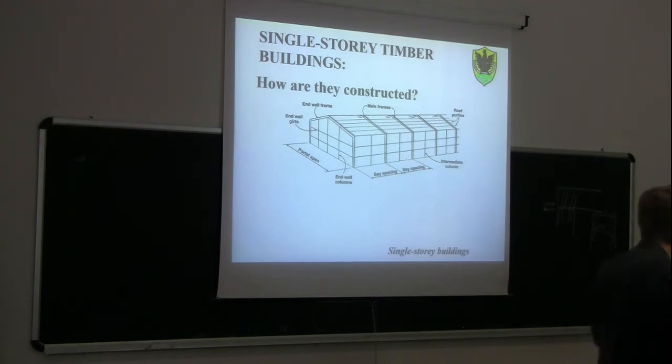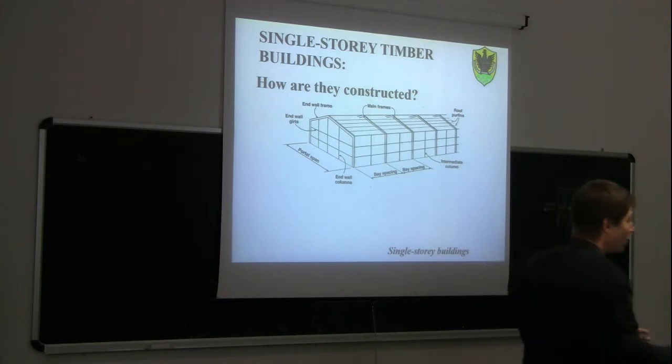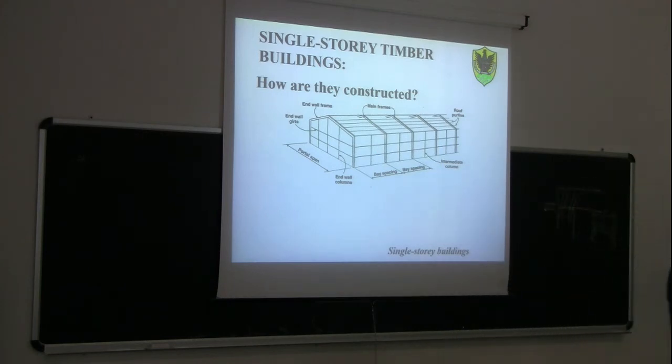Of course, the distance between those horizontal members here is really connected to the type of cladding that we are using. In some cases, there are examples of very heavy claddings using reinforced concrete panels. In this case, perhaps you don't need it because those reinforced concrete panels are like a cantilever. They are supported by a foundation here. They are very heavy, and they stand alone like almost a cantilever, I would say.